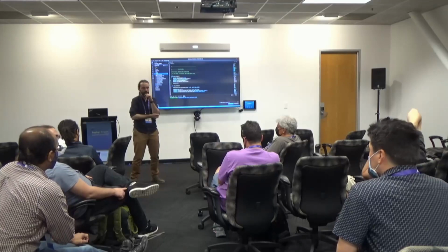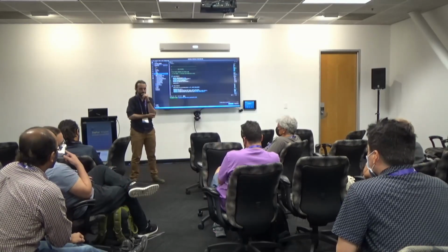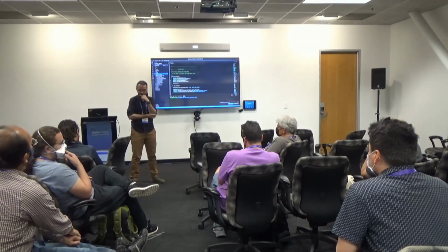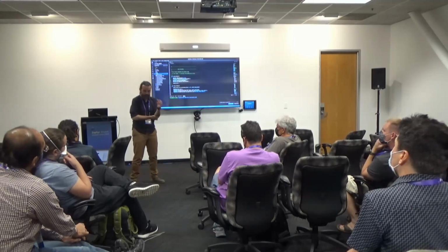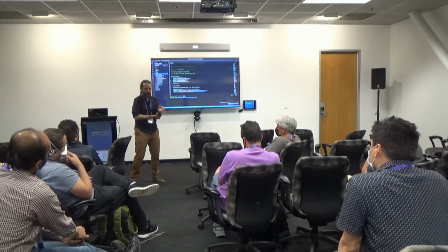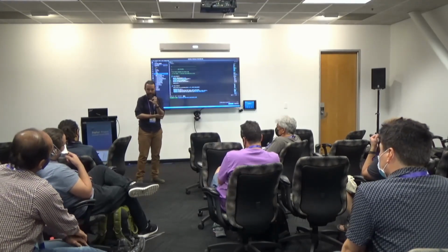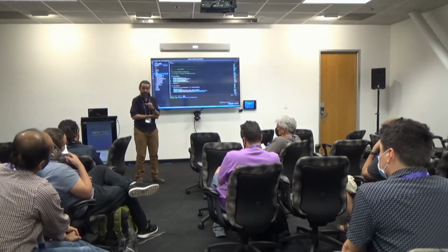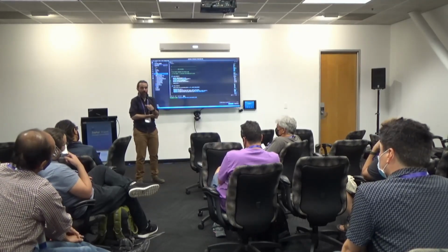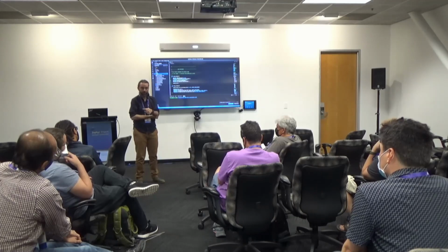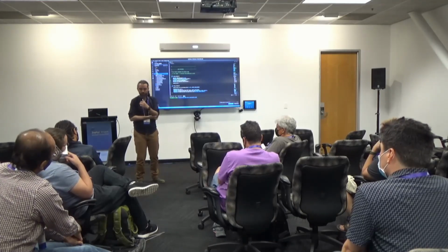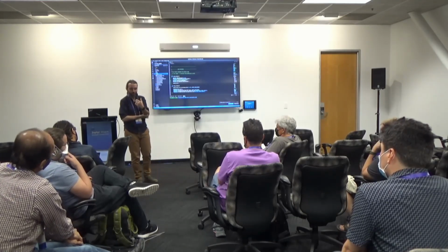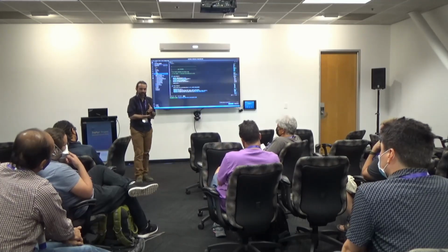Couldn't you use I/O for interrupts? It's a very good question why we don't use interrupts. The time criticality of power electronics obliges you to have deterministic timing, and if we use interrupts, you're no longer fully sure you're deterministic.